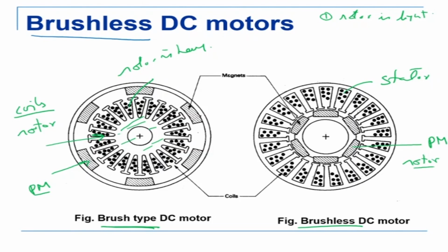Why? Because the motor would be rotating at very high speed, say maybe 3000 rpm. So if you want to brake the motor and reverse direction, or you want to control at that speed, it's very difficult. Whereas in the case of the brushless motor, the rotor is inside, so it has low inertia, it has low J. Now because it has low inertia, control of the motor, braking of the motor is much easier. So the rotor is light, so control is easy.